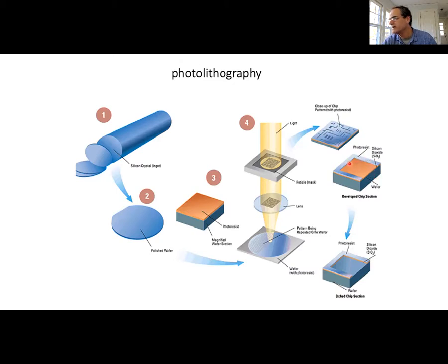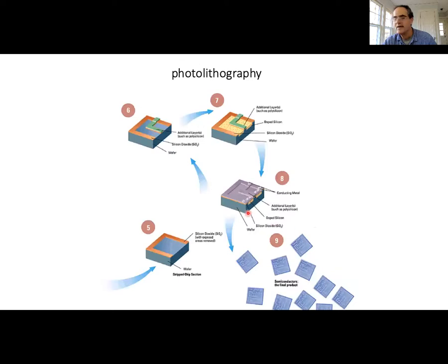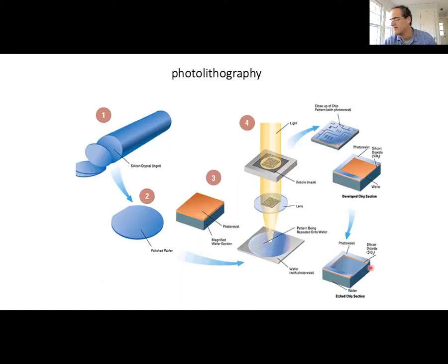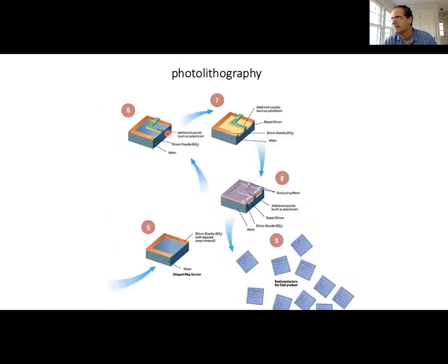Now we can use the photoresist as a mask for an etching process. So here the wafer is etched. The photoresist itself blocks the etch. So the silicon is only etched in the regions that are exposed. Then the photoresist can be removed, and the pattern now is left behind on the silicon, okay? We can use this to do steps like the following.